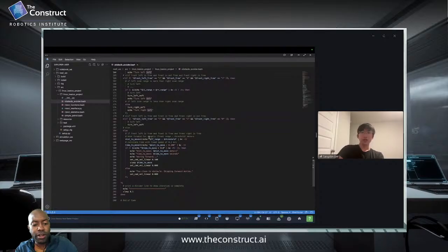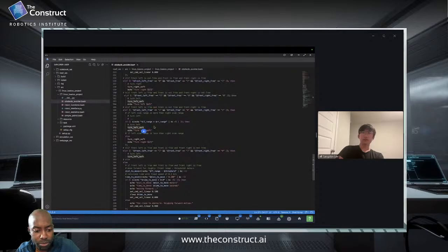So okay, you're saying that in the case we had where it had to reverse, the left was not free, front was not free, and right was the only free place to go, right? And if it had left enough distance, so if it had left 0.3 meters in front of it, I thought it could have rotated nicely, right? But we noticed that it reversed, so that's what I wanted to understand. What's going on there? Did you think the threshold was not enough for that specific case, and how did you get to that?